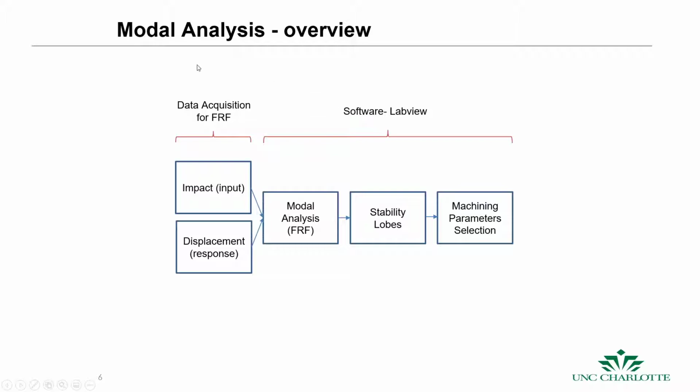This is an example here from our research of how we can do some modal analysis by taking an impact hammer where we whack a structure and then have a sensor. In this case, this is an accelerometer that is integrated twice so that we can get the displacement.